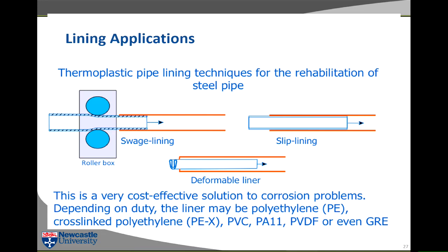Exactly the same as those. So about every metre there'll be a thermoplastic cable tie which goes around that, which stops the thing from springing up. So you pull that into the pipe. You've completely got it inside the pipe, and then you pressurise the liner. All these little ties break, and the liner will then expand and fill the pipe.